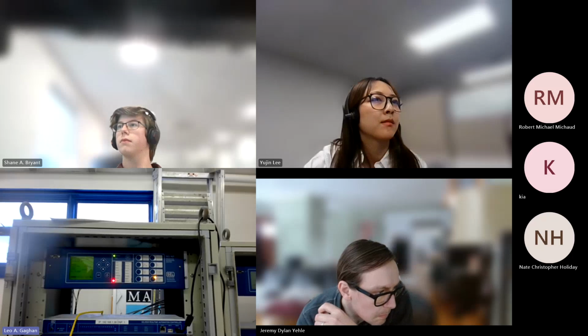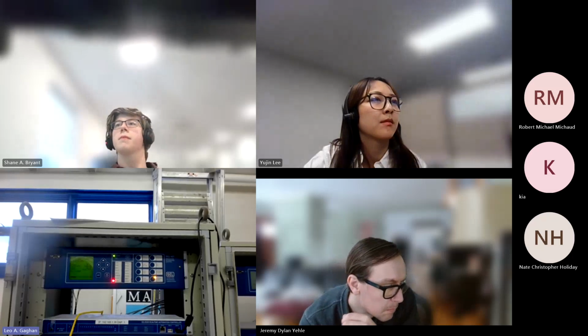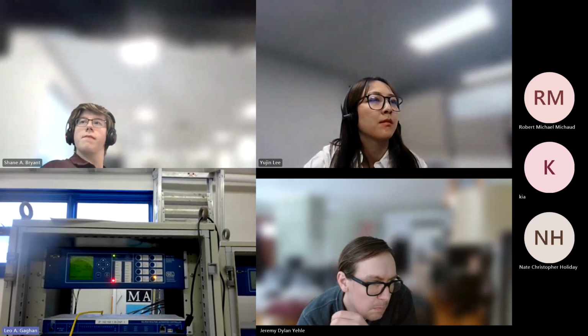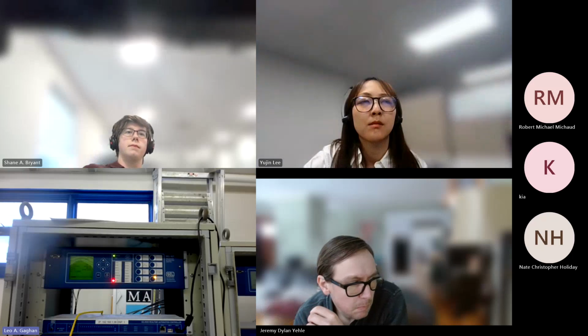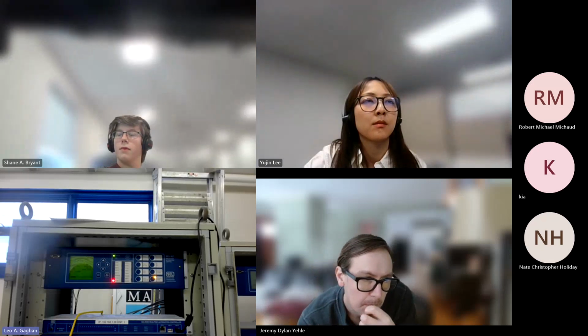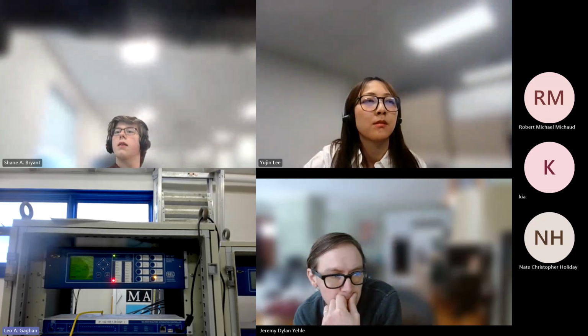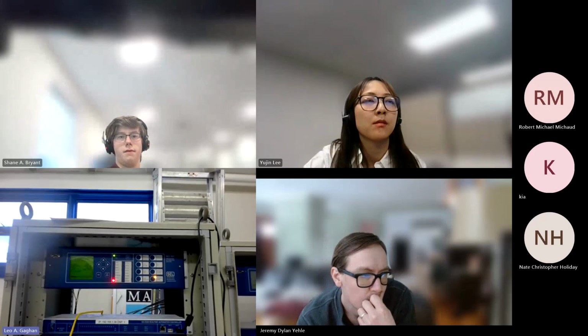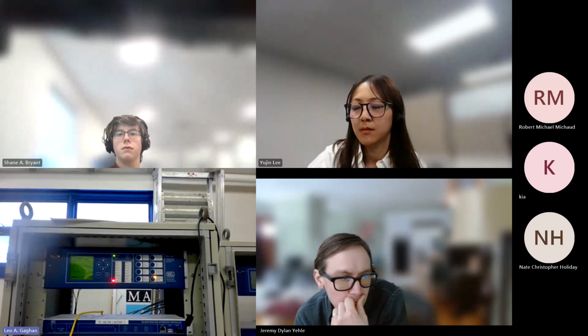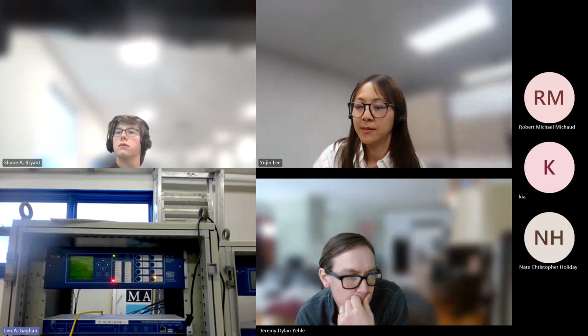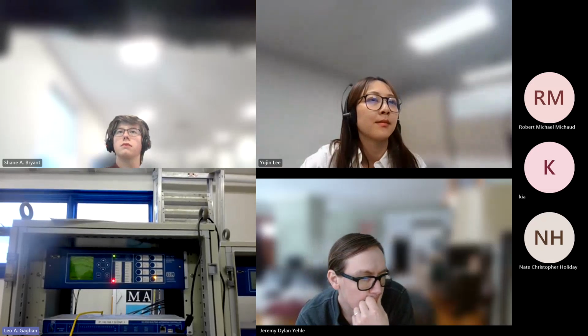There's no point in closing a breaker unless it's already open. We push the push button for 1 full second, and the breaker is open, and we're not being tagged hold. That's another function we'll get to. And we're not in control switch mode, we're in relay mode, then it will close the relay.